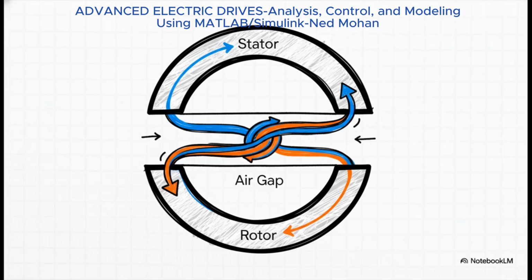Now, listen up, because this next point is probably the most critical concept for tying our whole model together. Think about it. For flux from the rotor to link the stator, it has to cross the exact same air gap as the stator's magnetizing flux.